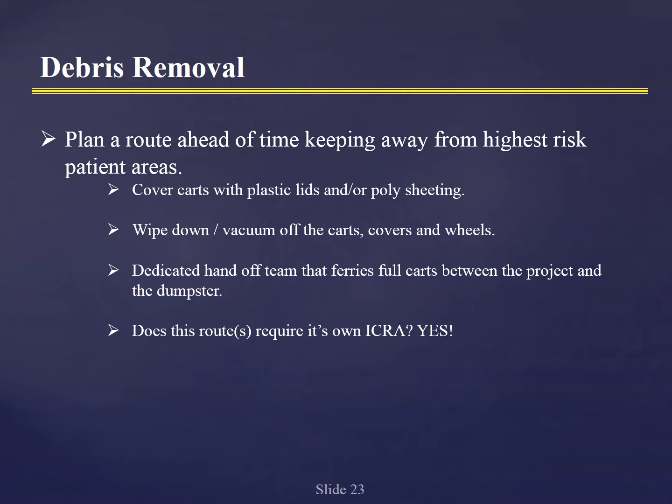It's so common to sometimes miss that the debris in the space and the creation of dust and dirt in the space obviously is directly related to everything leaving the space. So you're basically extending your construction area wherever that debris is moving. So it's really kind of in its own regard another project as things travel through your facility.